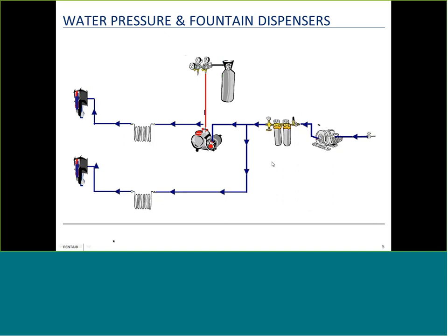How those are typically placed is we place the water booster between the inlet water supply and the filtration. And the reason why is, A, we want to boost the pressure to the filters so that they get maximum life out of those carbon filters, rather than low pressure trickling through and then feeding the water booster. Also, if the water booster system develops any taste or odor issues, the carbon filters will handle any of that taste and odor issue before being dispensed.